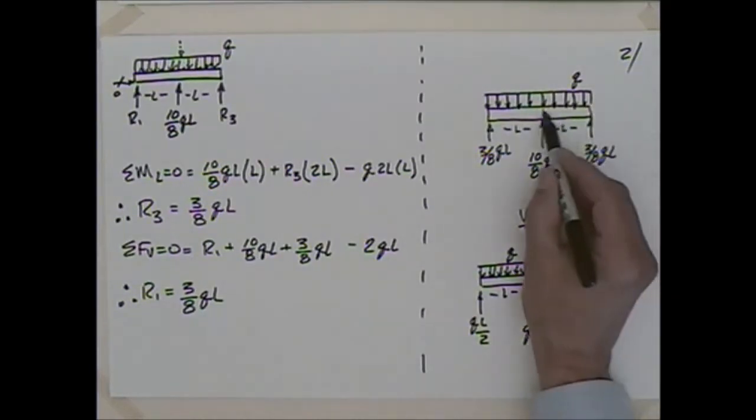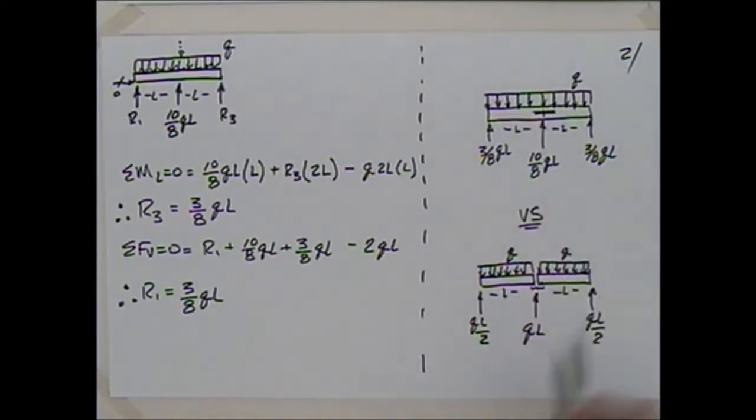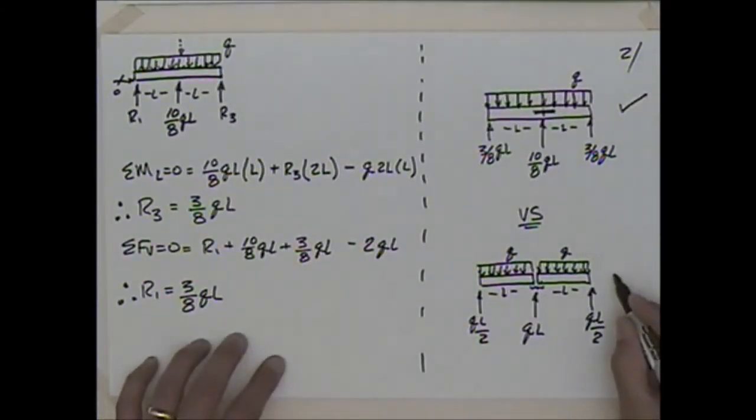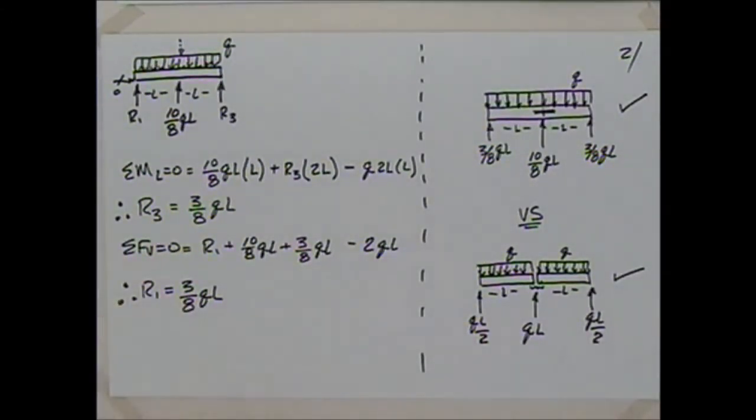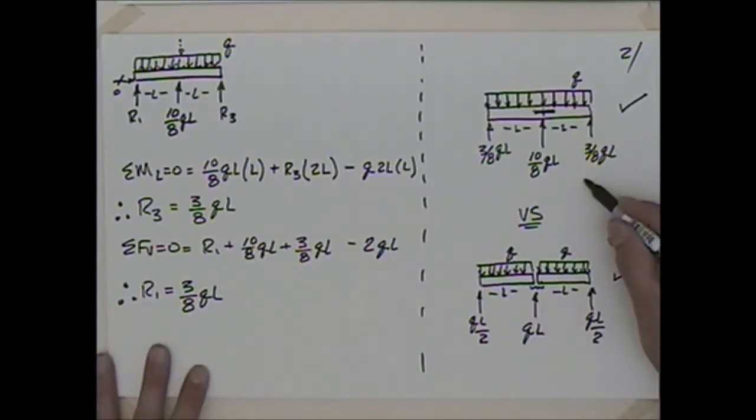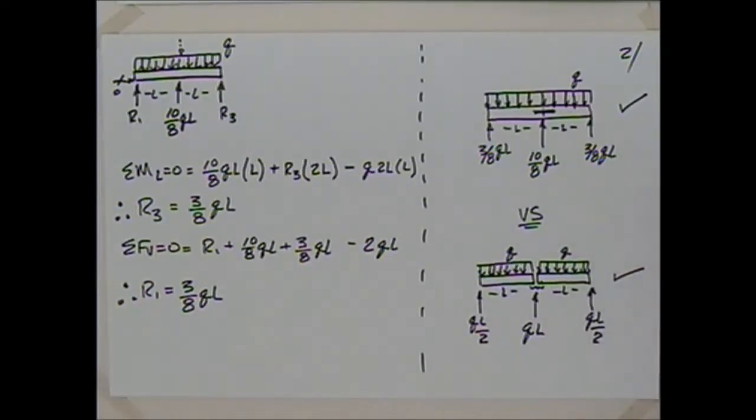Usually you just prescribe cutting through that and then tie it together with some sort of a strap so it doesn't separate in an earthquake or something like that. But sometimes this is an advantage and sometimes this is an advantage. And the biggest thing that hopefully you take away from it today is that they are different. A continuous beam is a statically indeterminate situation, and it's going to net different support reactions. And then if you were to take this one step further, it would have a different shear and moment diagram. They would have different shear and moment.